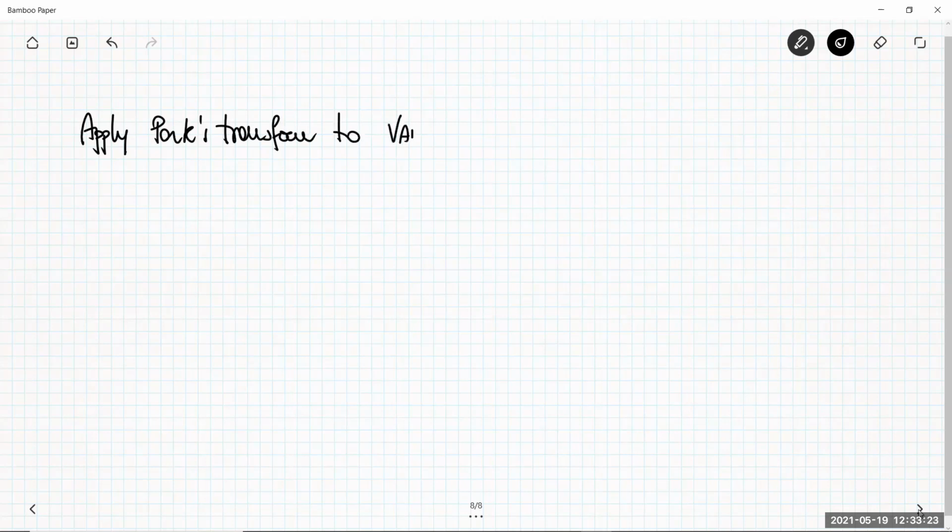To VAB, VBC, and VCA. Remember that we can have the switching function. Let me call this switching function V1, the space vector obtained by applying the Park transform. This is C, so 2 divided by 3 by our space vector amplitude-invariant definition.